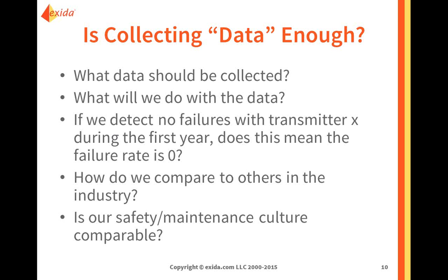Why do we need to collect data? Which is sometimes a huge challenge to communicate to operation and maintenance people. Say, hey, yes, I realize that simply resetting that transmitter, powering it down, powering it up, or the other way around, solves the problem, but you really need to record that piece of information because that could be an indication of a serious problem with that transmitter. And not everybody may be aware of that particular scenario.